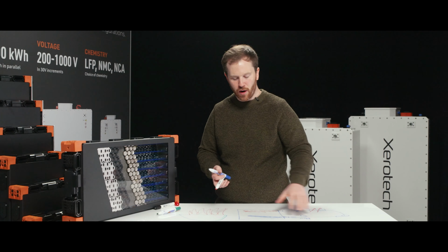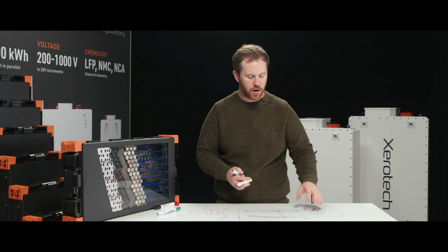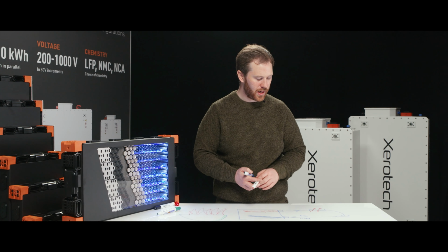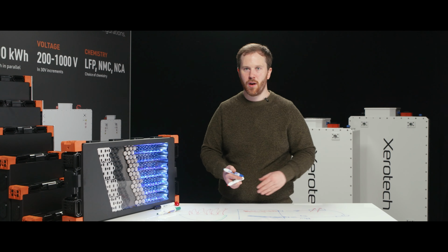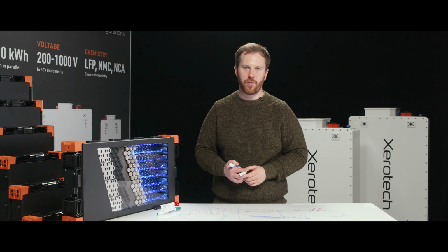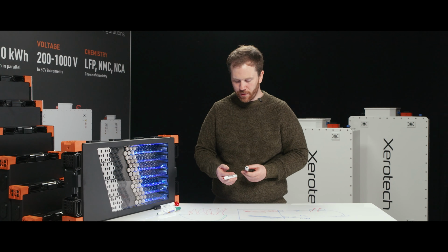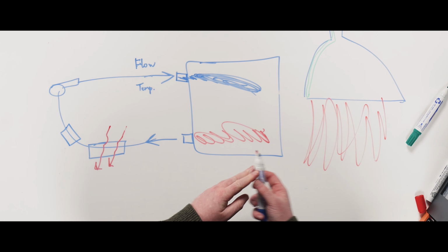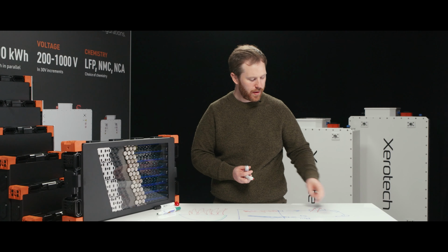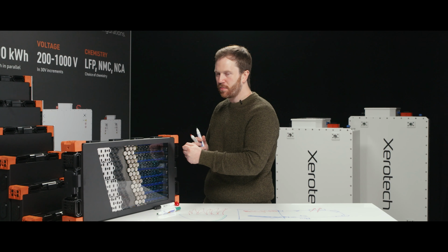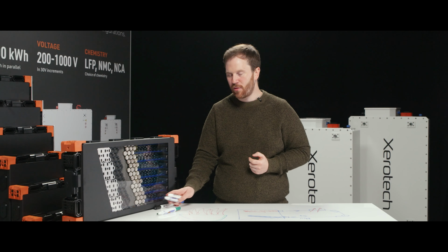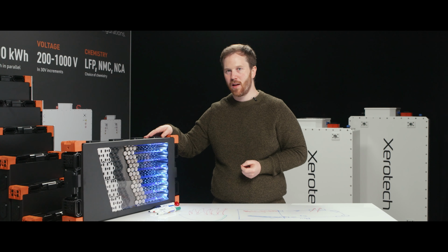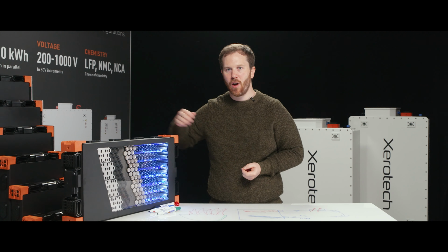So overall, battery thermal management systems have a number of different subsystems inside of them. Another heat exchanger that either raises or decreases the temperature of the system. In some cases, it might just be a heater. It's like having that kettle we spoke about earlier inside the battery, where you just preheat it. And that's where some battery systems may have internal heating, where they use electric heating mats or an electric coolant heater.